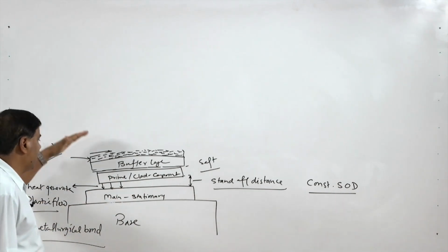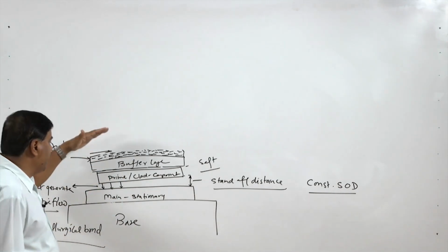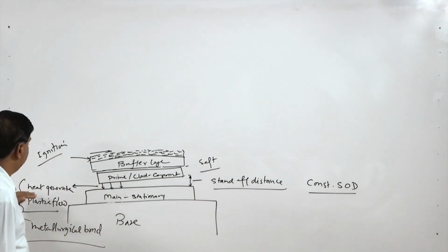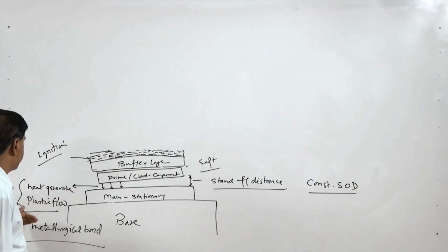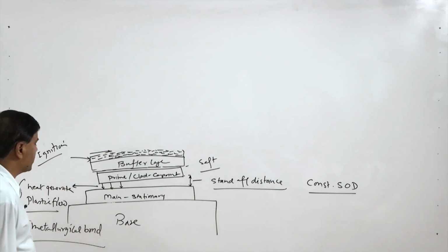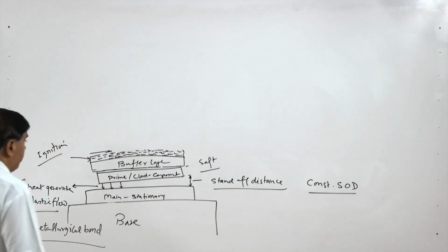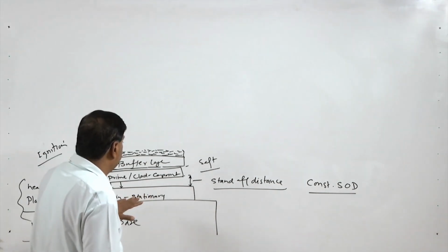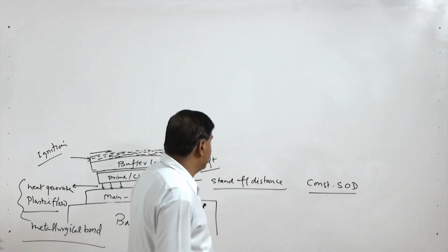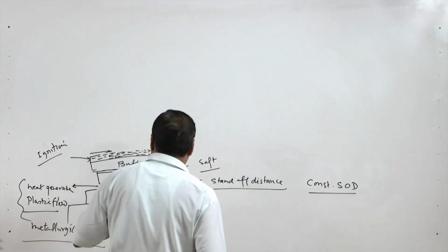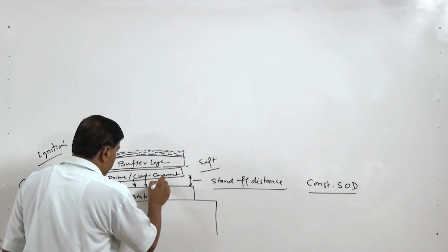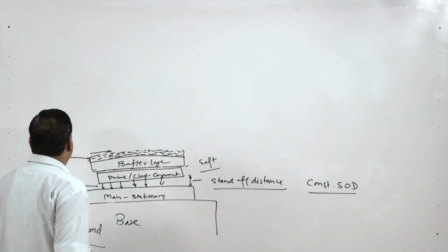And so, after explosion, when the impact takes place with sufficiently high velocity, heat is generated, and plastic flow at the interface facilitates the metallurgical bond. So, this is how it works in case of the constant standoff distance. In this case the plate will be moving from one end to another sequentially as the